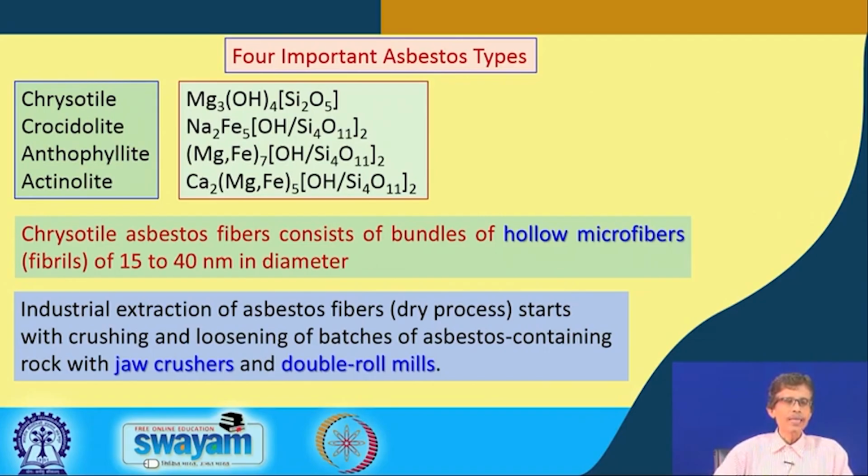So first one basically, the chrysotile, is your typical material which is basically magnesium silicate. As we all know, we use different types of talcum powder day to day. What is talc? Talc or the talcum powder is nothing but hydrated magnesium silicate. So this is also a sort of hydrated magnesium silicate of different structure. So the chemical composition of this asbestos type is typically that of talc or talcum powder, made of only magnesium silicate which is hydrated to different levels.